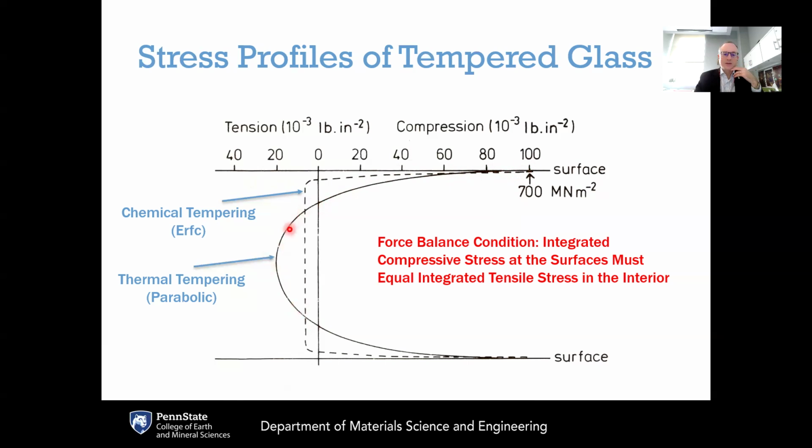And with this stress profile, if you integrate the compressive stress at both surfaces, so integrate these approximately triangular regions at the upper surface and at the lower surface, that integrated compressive stress must be balanced by the integrated tensile stress in the interior of the glass.